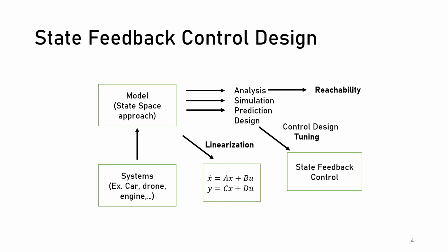But anyway, for many systems, many systems are linear. Then when you transform from ordinary differential equation into state space, you already get this linear form. Okay. For stability or reachability, there is a way to analyze on the original equation if it's non-linear, but if it's linear, we have a simpler way to analyze the reachability.